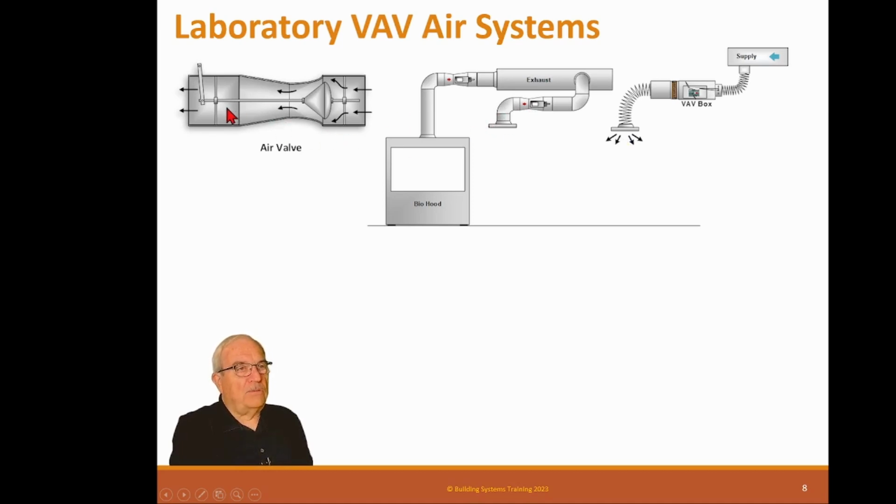These all use these special orifice valves that are very symmetric and very accurate and very fast. You can't put a box in here that has the standard old HVAC actuators that take 60 seconds to rotate. Not going to work. These have to be fast acting. Most of these are 15 seconds, 10 seconds to open and close, so they're very, very fast. These originally were pneumatic, which are instantaneous, but we've gone back to electric, and so they have to have fast actuators to work.